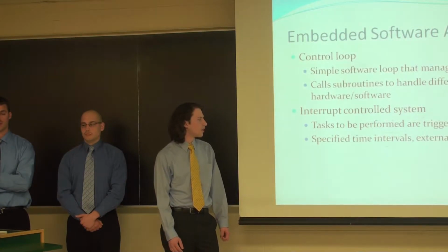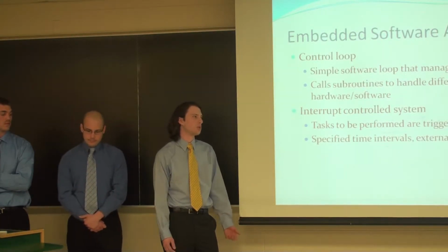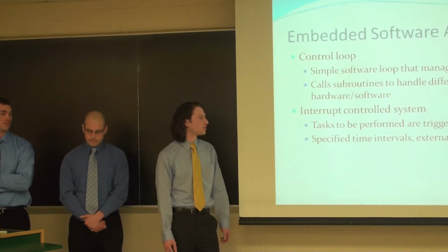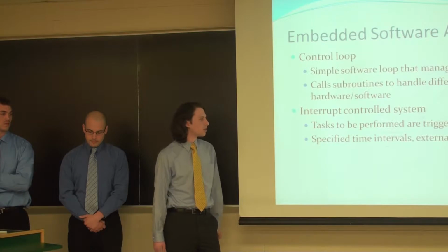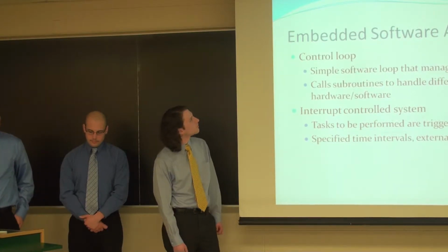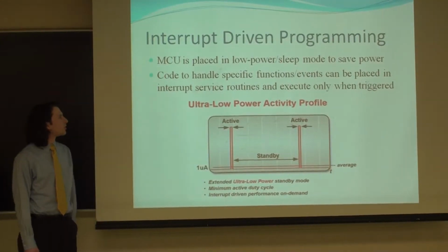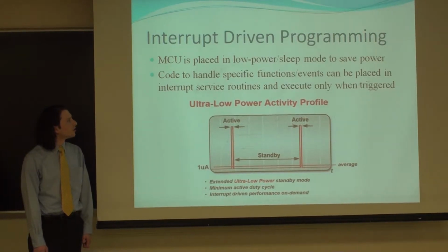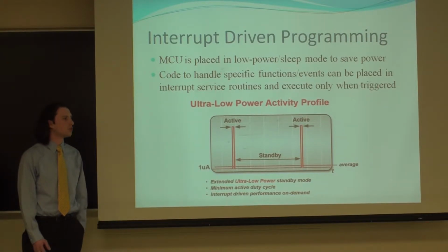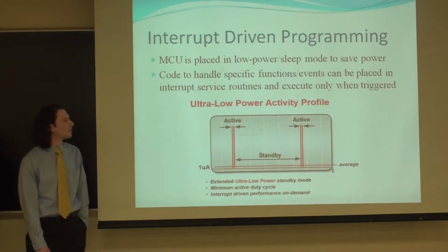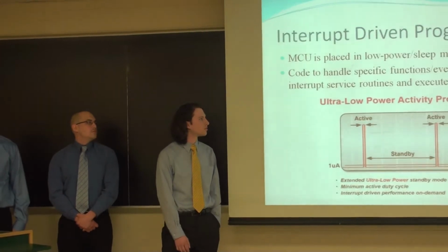Another main architecture is an interrupt control system. In this architecture, the tasks and functions that have to be performed are triggered by events such as pre-programmed timers or external inputs. So whenever they're triggered, an interrupt is called that executes the necessary code. The architecture that's more conducive to low power designs is interrupt-driven programming. The microcontroller can be placed in a low power or sleep mode to save power when intensive processing is not required. And then the code that handles specific events or functions or tasks is just triggered by whatever interrupts are